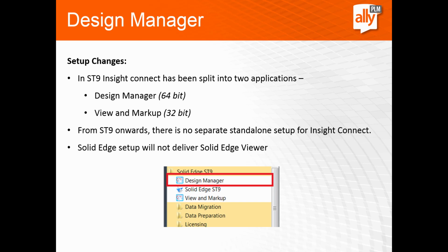In ST9, our Insight Connect has been split into two applications, the Design Manager and also View and Markup. Just a note, from ST9 onwards, there's no separate standalone setup for Insight Connect. Also, when you install Solid Edge, it will not deliver the Solid Edge viewer anymore.